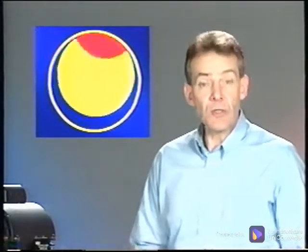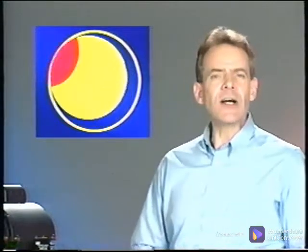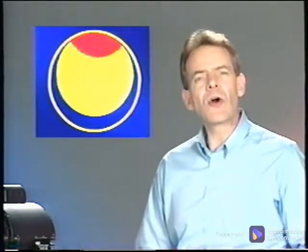Unbalance is the condition when the center of mass is not the center of rotation. This uncentered mass causes one side to be heavier, and centrifugal force pulls on the system, causing it to move or vibrate.